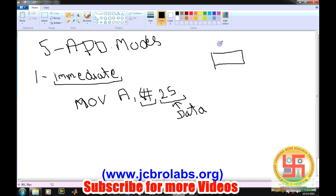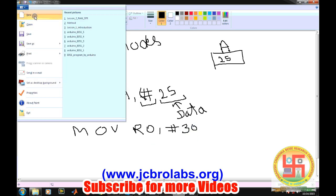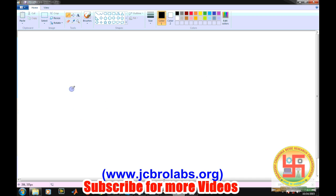This is the accumulator register, so the content of the accumulator will become 25. This is the immediate addressing mode, meaning the data is directly transferred into the register. If we write MOV R0, #30, then 30 will be directly transferred to R0. This is also the immediate addressing mode. Then the second addressing mode which we have is the register addressing mode.